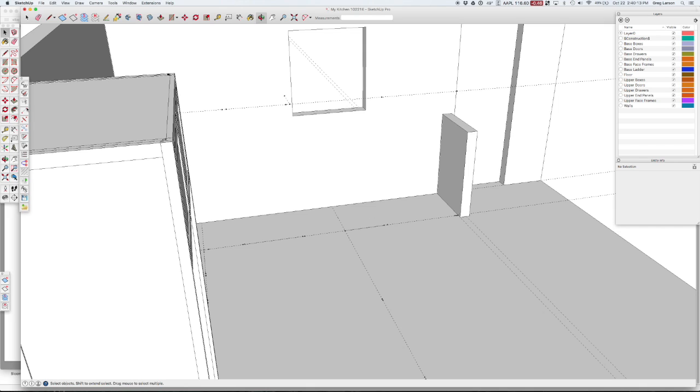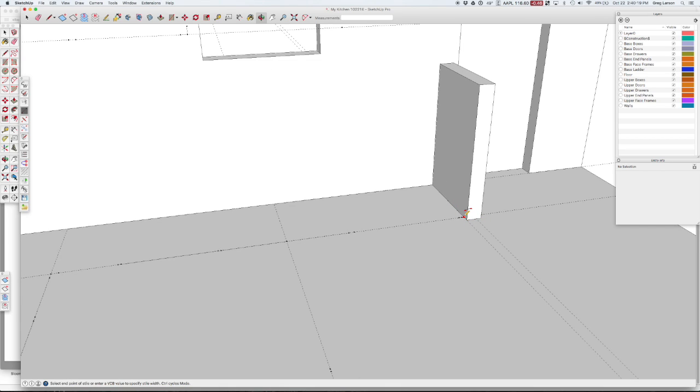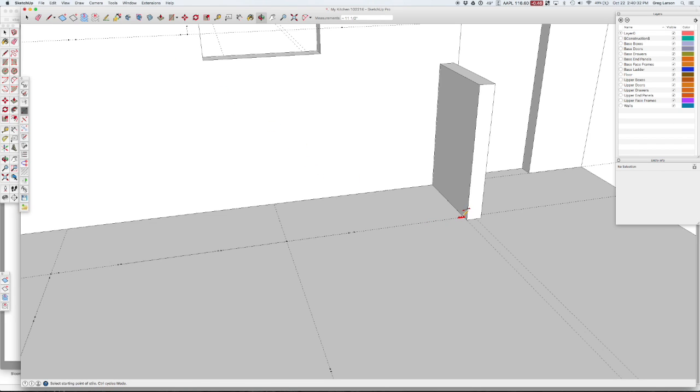And I'm going to go back to my story stick. I'm going to undo the one that I did because it was done with my frameless settings, and I'm just going to redo that. So pick a right end wall style, and notice it knows how big a wall style is for face frame, so it put it 1.5 inches wide, which is what we have it set for.